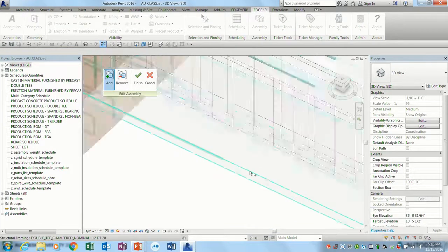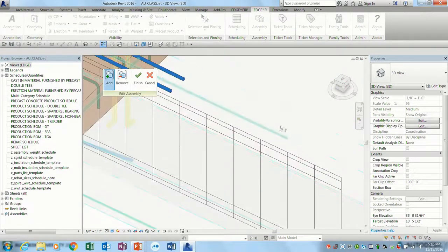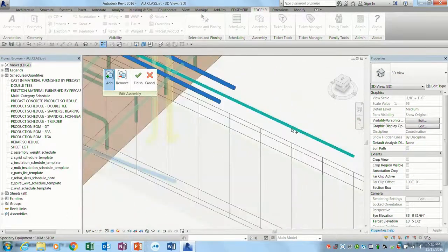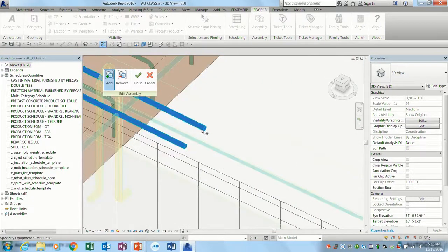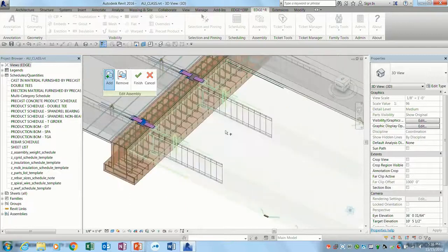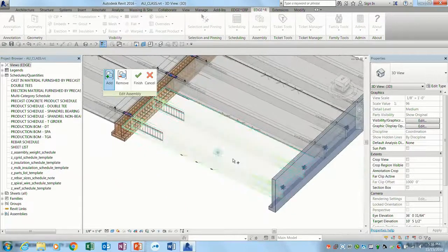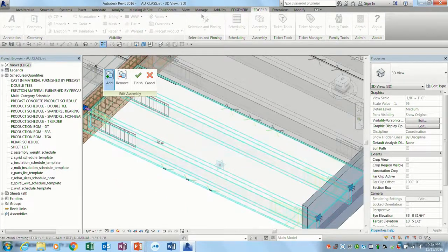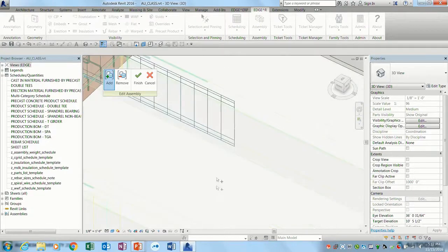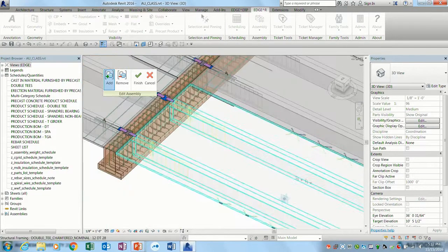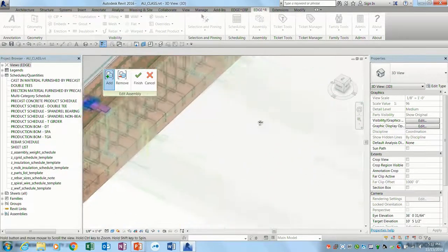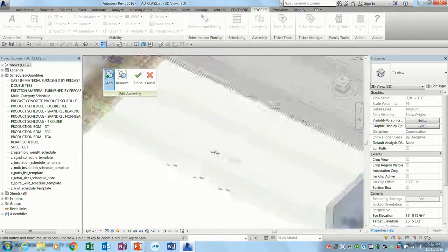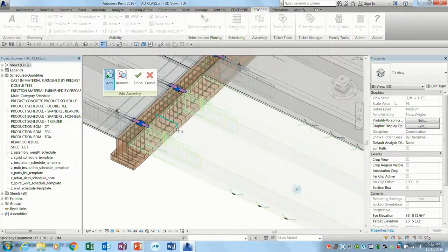You can speed this up somewhat with some crossing selections and some box selections. You can be a little bit smarter than he is about it, but I really wanted to see what it's like. This is a pretty simple model, right? Our models are much more complicated than this in general. So being able to tab in and see these things, scrunch your view down so that you can see what you're looking at and not get confused with other elements, is important, because it can be easy to pick the wrong elements to pop in there.